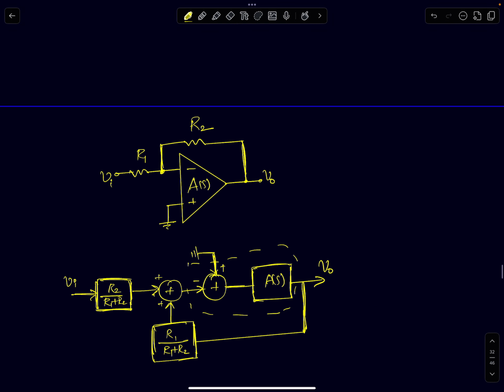Now, finally, to the third amplifier architecture. I'm just taking some very common circuits that we have analyzed so far and showing you how their frequency response characteristics will look if you assume the op-amp has a finite UGB. In the case of an inverting amplifier, it is not as straightforward. I can't just directly draw a closed loop model like this. The closed loop gain is not just 1 by beta for inverting amplifiers; it is slightly different.